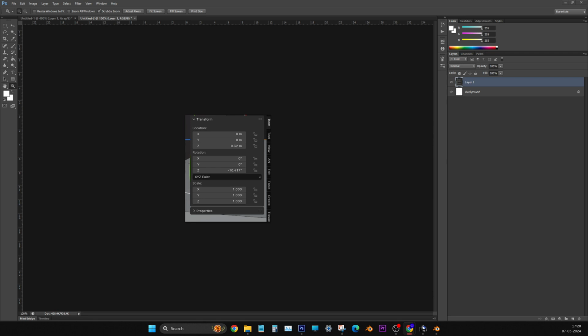So undo it. We have to see the array settings again, on the right side. You keep doing undo. See, you are seeing the array settings, no? What happened when you pressed the apply button in the array modifier dialog box in the right side properties panel? Blender understands: you want me to make all the instances real.